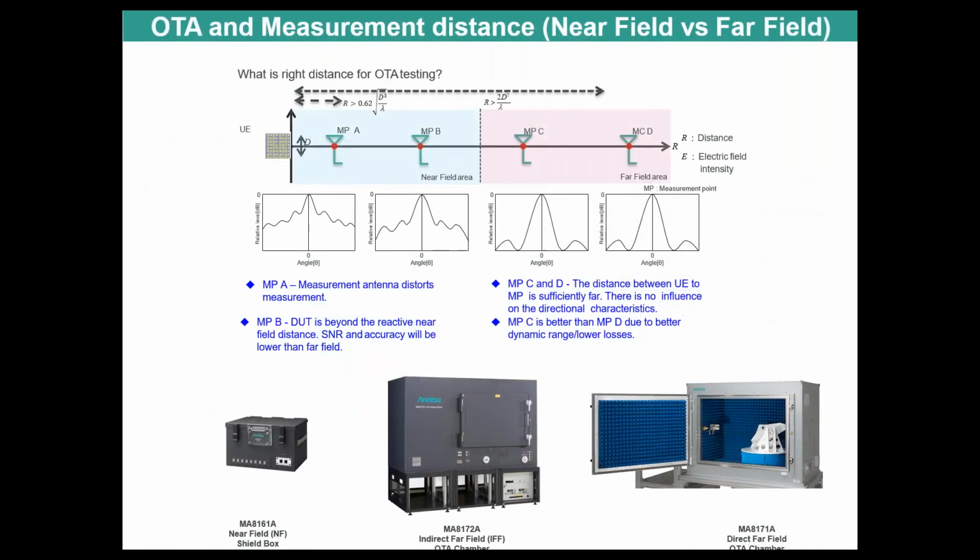And then I wanted to bring you onto the concept of OTA testing, near field versus far field, right? As we go into millimeter wave, it becomes necessary to test over the air, because first of all, your antenna array is really tiny. You could have an 8x4 antenna on the order of 3 centimeters, and it may be difficult to connect a device to it. Even if you're able to connect a cable to that antenna port, the propagation loss will be too high to do any kind of good measurements, right? So OTA testing is important.